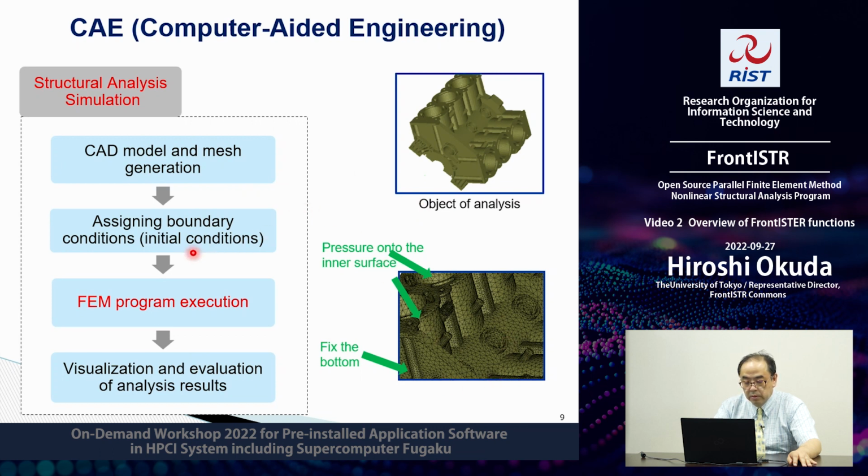And also you need to specify the boundary conditions or material constants like this. Then you would execute the finite element program like FrontISTR. And once you obtain the computational results, like displacements, strains, or stresses, you would visualize and evaluate the analysis results. And this CAE process is repeated in such a way that the final design is obtained.